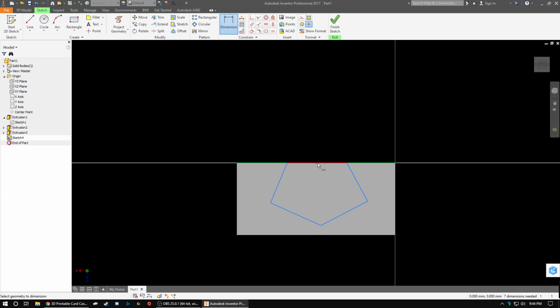And I want this to be, say, 20 millimeters wide. I want it to go down 25 millimeters. I want this to be centered around the center point, so I select point to point, and I can't select an edge or a line, so let me project the middle points. I'm just messing around so you can see what's going on here.